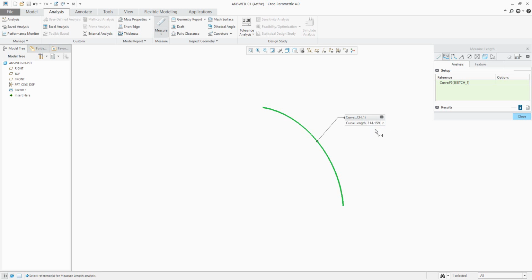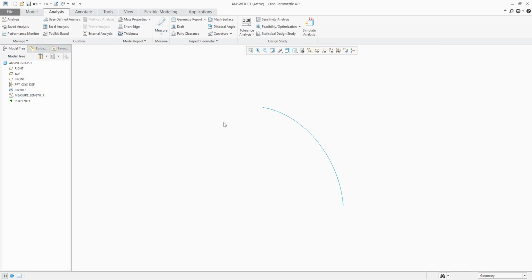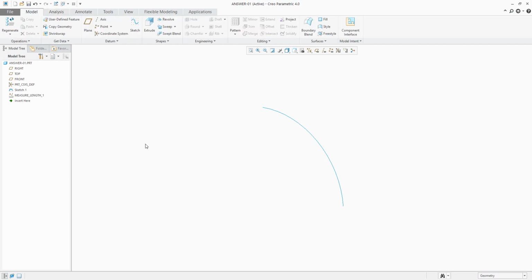So you can copy this length and you can reuse this length for the extrude feature. I like to use some advanced options, and one of these advanced options is that if you select this drop down menu, you can make a feature. So select the name and confirm OK. The system will create for you the feature in the model tree, and the system will create for me the parameter length. In the future, if it is necessary, you can change the name or define your custom one. Yeah, I will use in the future this analysis for the length of the extrude feature.